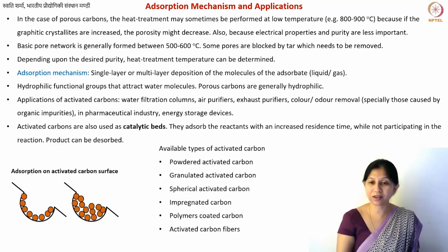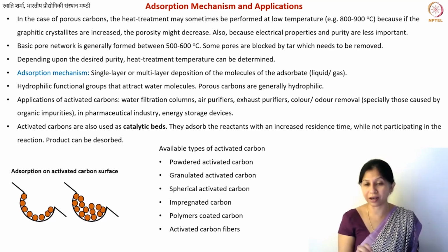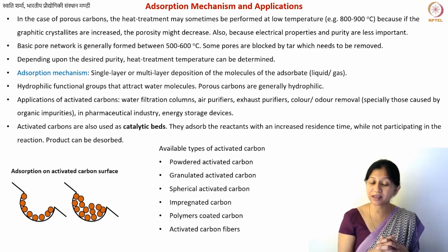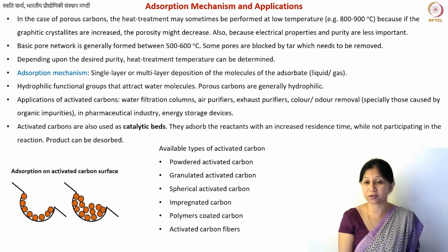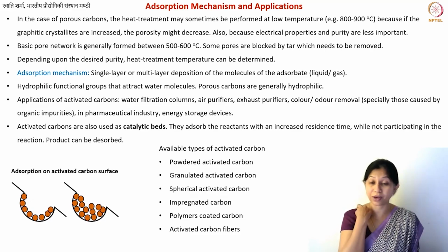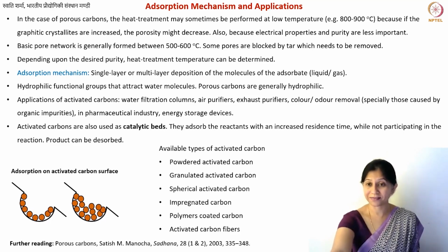Okay. What is also very important, this is something we are going to learn in the carbon fiber section, that we can activate the carbon fibers as well. Carbon fibers, of course, some of them are made of natural polymers like cellulose, and they are also made of some synthetic polymers. We will talk about them. So activated carbon fibers is also a very interesting field, because carbon fibers already offer a lot of surface area compared to a bulk solid, and if you further activate them, then you have a very large surface area available, and then you can make really very high efficiency adsorbent structures.